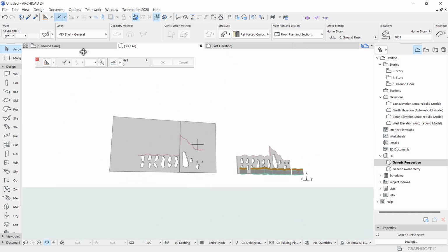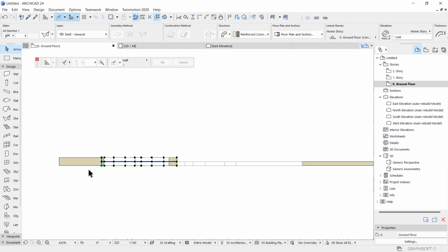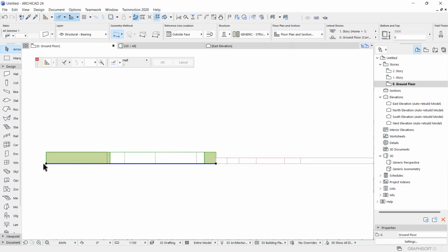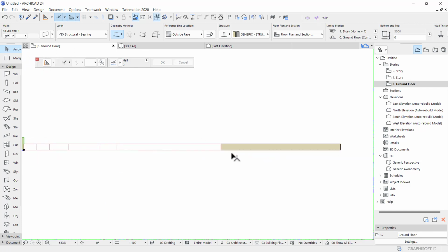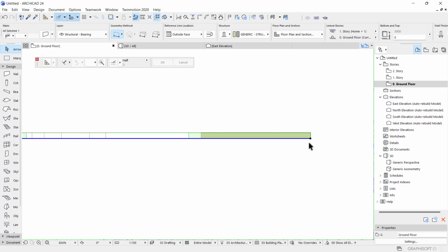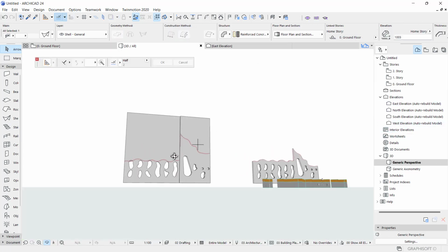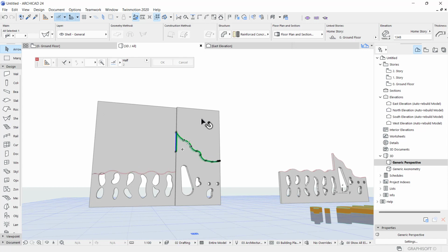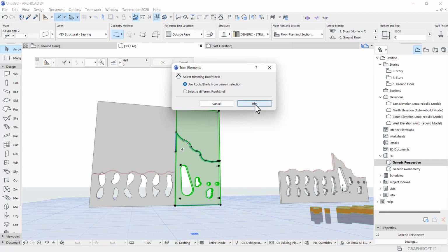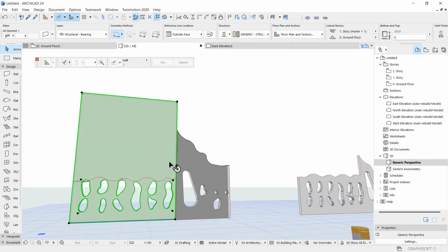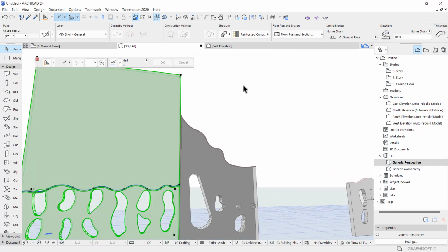if you want, you can shorten the wall. Like on this end, I can click it and shorten it to there so that it is the same as our move. Then let me cut first. So this and this, and Control connect, not Control left click, connect and trim. Then this and this, and connect and trim.